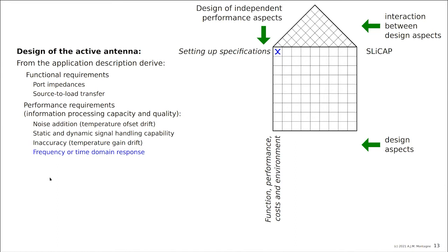The frequency or time domain response: we basically went for a maximally flat frequency response in many cases, but that is not always required. Weak nonlinearity can be specified in various ways: harmonic distortion and intermodulation distortion. Intermodulation or gain compression can be another effect, or just nonlinearity. We have discussed all these definitions in the bachelor course.